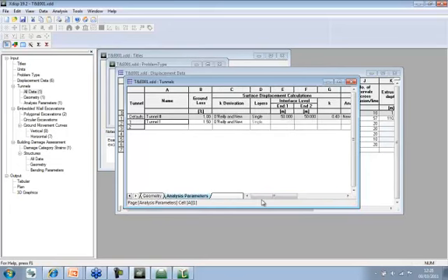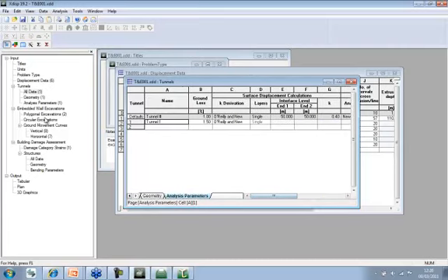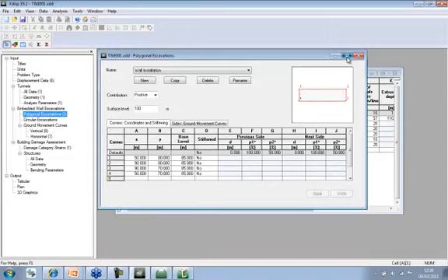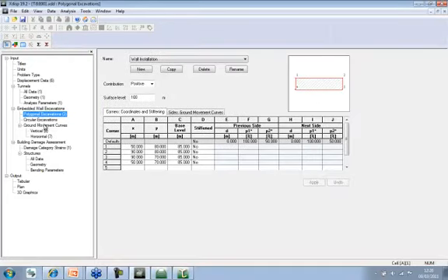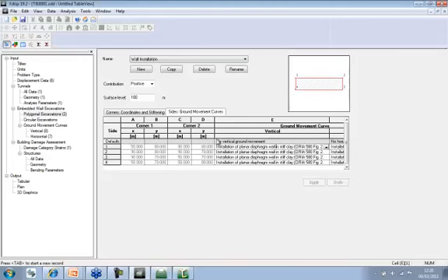And there's the analysis parameters here. So, as I said, the volume loss and the K parameters are all in there. The embedded wall excavations are also of interest. So we can have circular excavations as shafts. We've got the initial excavation installation of a wall, and we've associated the Series C580 curves to it. So there you go. We've got the installation of a planar diaphragm wall in stiff clay.